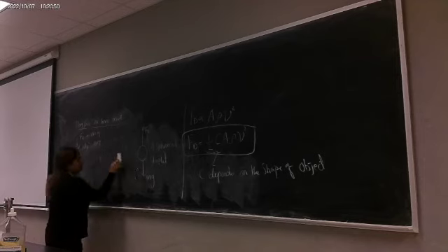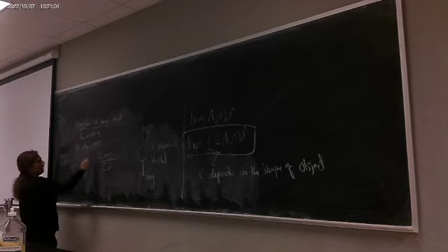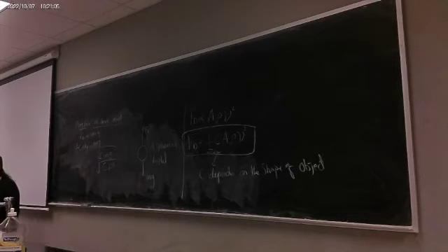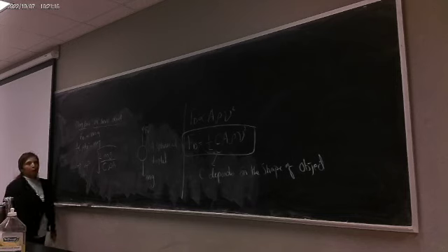V will be equal to the square root of 2 mg over C rho A. Correct? How easy to find this equation? All you have to know is Fd. This velocity is called the terminal velocity.